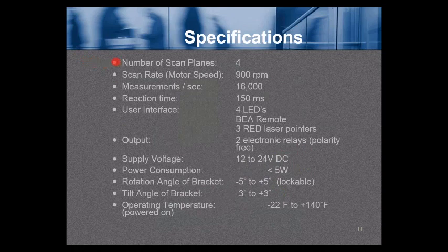Specifications: number of scanning planes, or number of laser curtains, there's 4. The scan rate, or the motor speed that's spinning and rotating inside of the sensor, 900 RPM. Therefore, measurements per second are 16,000 measurements per second. The reaction time of the sensor, very fast, 150 milliseconds.